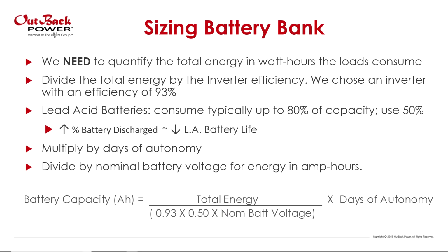And with some manufacturers, you have to read the literature closely, because some have a requirement for maximum depth of discharge with their warranty. So really know what the literature says for the batteries you decide on. Some off-grid designers have larger battery banks so that they only discharge 30% of the batteries, with the intention to extend the battery life. There are other technologies such as lithium ion that have the capability to discharge 100%, but there are trade-offs with that, such as initial cost and complexity.